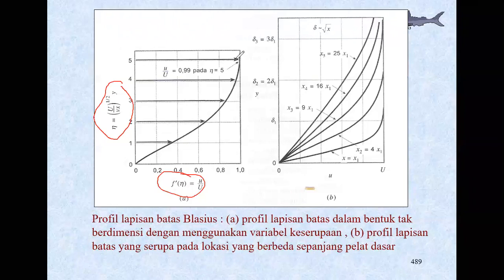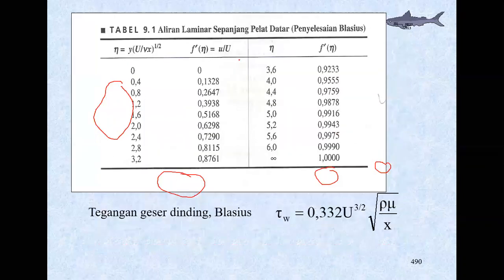So you implement this inside the boundary layer until the delta point over there. If you have a different value of velocity compared to the maximum velocity, then you will have a different y value, a different thickness. Okay, so that is the Blasius solution.